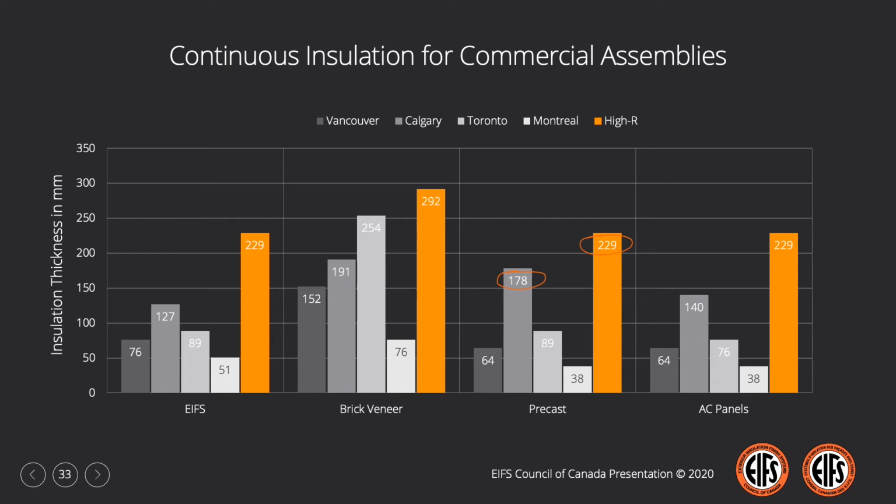So when we look at the SPF installation standards, we have a maximum single pass thickness of 50 millimeters. A cooling period of no less than 10 minutes is required between the first and second application. No less than an hour must be allowed prior to the application of a third coat. If an additional pass is required, a cooling period of 1 to 4 hours is required, and that would be the cooling periods required to achieve our 7+ inches in the Calgary condition.